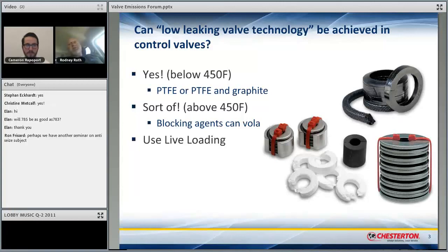Well, the camera can't see that. If somebody's at 1,000 ppm, the camera's fine. But it's not ever going to replace the handheld monitoring device until it becomes something anybody can use, not some super high-tech guy who's been doing it for 30 years. I've talked to some very amazing camera guys, and I've been told the best guy in the world can't see below 400 to 450, no matter how hard he tries.